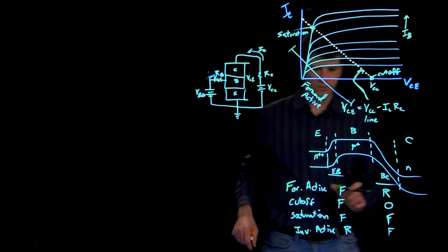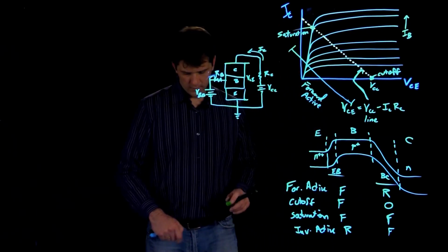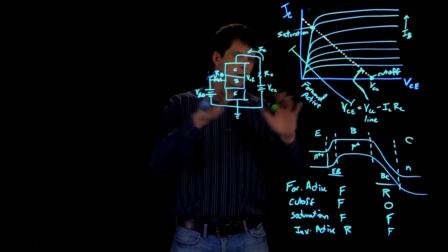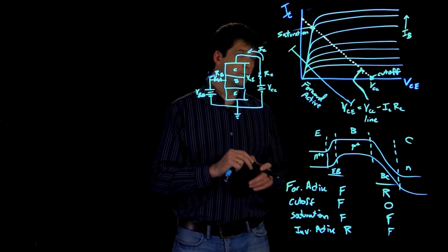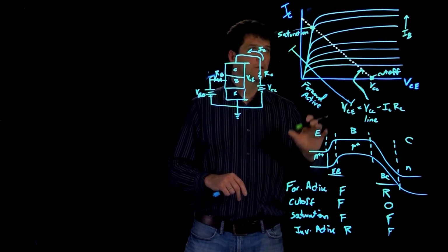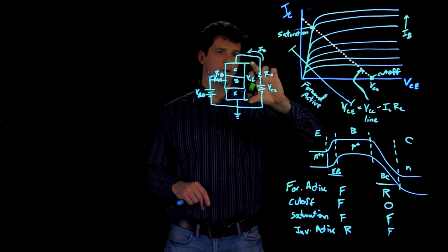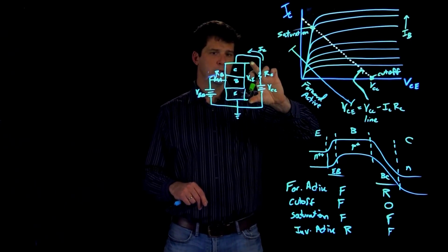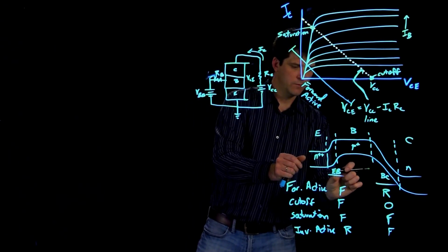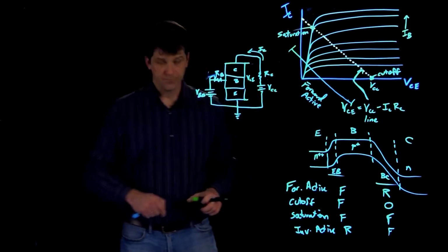And again, we would have to physically flip the transistor. So that relates the concepts of regimes of behavior and the IV curve for the device here, and written on the x-axis in terms of the total voltage across the transistor, which is going to be internally the sum of the voltages across the emitter base junction and the base collector junction here.